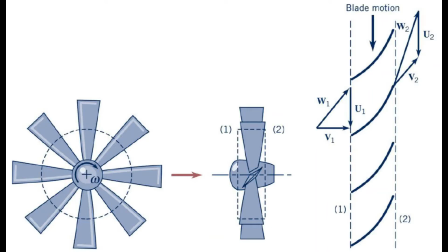And here we have another velocity diagram, this time from a windmill. So again, fluid coming in left and right. I have my relative velocities, W1 and W2, still being tangent to those surfaces on the way in and the way out. Still have my overall velocity, V, equal to U plus W in both cases. In this case, we can see that the energy is being taken out of the system because the turbine is moving due to the force exerted by the fluid. So windmills obviously work because the wind is pushing on them, and as it pushes, the windmill moves, and that energy is being taken out of the fluid.